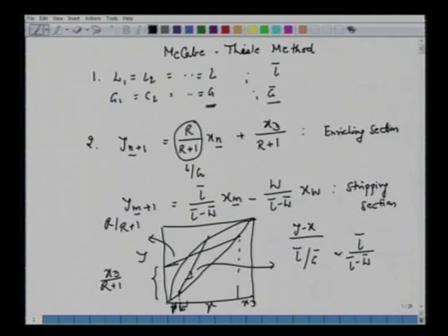What we would like to do now, given this feed composition, is find the equation of this line. That's called the feed line. The feed line is obtained by making a species balance and an energy balance at the feed tray. So let's do this.